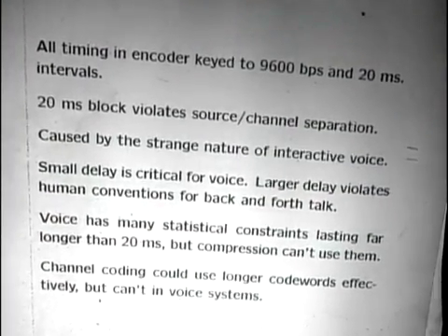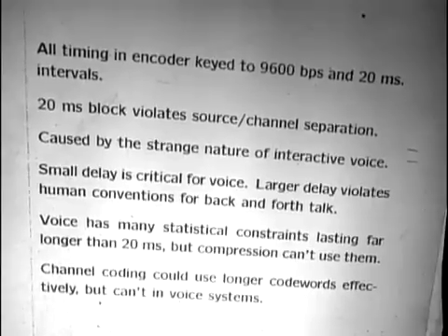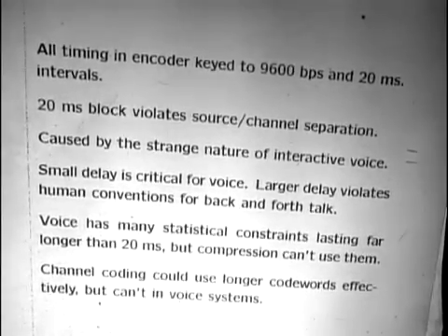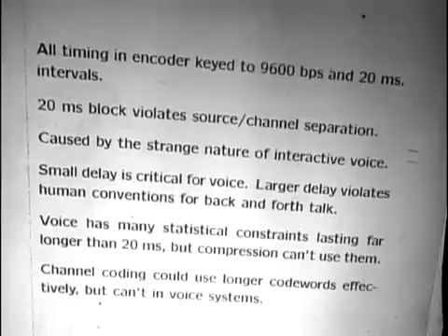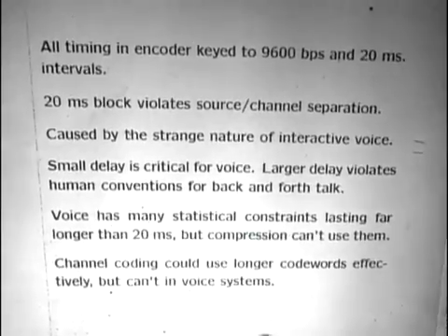So the point is here, we've talked a great deal about all of digital communication sort of being generated from people's realization that they ought to separate voice coding from channel coding. In other words, there's this binary interface between all sources and all channels. This is a violation of that. And all cell phones have this violation. They don't have this pure separation because all of them face the fact that to do this small delay, anytime you want to get small delay, you have to have some mixing of what you do with the source and what you do with the channel, because the delay has to be some combination of what happens in both places. Okay, so we do have that violation, and it's because of interactive voice.